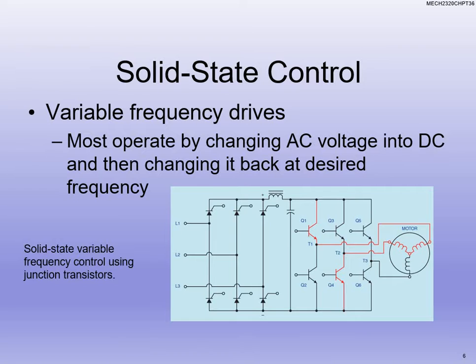Just looking at the schematic here, on the left hand side, the little triangles with the slash in front are the SCRs we've talked about, the silicon controlled rectifiers. The little transformer-looking inductor piece is the choke, which helps the flow through of what we're doing. On the right hand side, there are 6 of them, T1, T2, T3 connected to that.